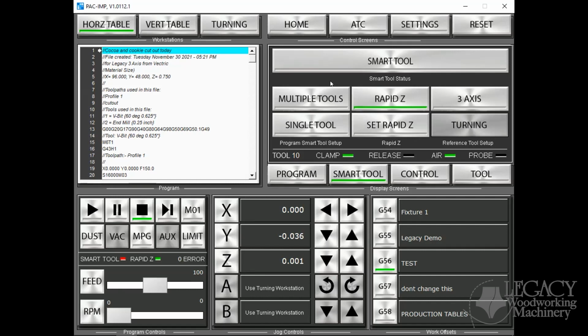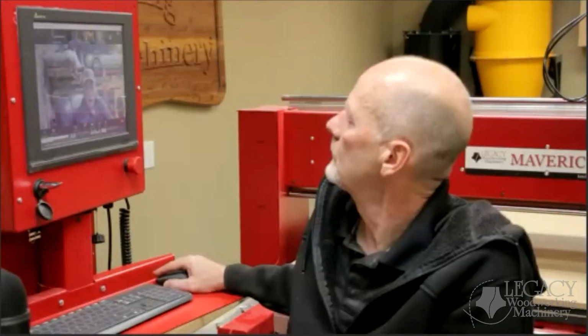Could also have his program set for bed and trying to set it on surface. Yeah, that's true. That's why you have to match. If in the program you set the Z0 on the bed, you have to set up on the bed. If it's put on the top, it has to be on the top. If you say you set it on the surface of the material and you put it on the bed, it's going through your table. You're exactly right.